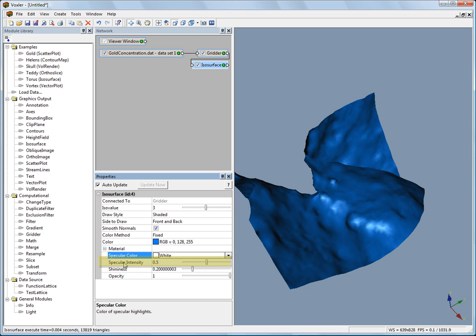The Specular Intensity option controls how much directional light shines and reflects on the surface. Increasing the specular intensity results in strong shadow effects and more pronounced shiny or glare spots. Decreasing the specular intensity results in a dull surface. To change the specular intensity value, click on the dragger and drag it to a new value. Alternatively, highlight the existing value and type in a new value. The values range from 0 to 1.